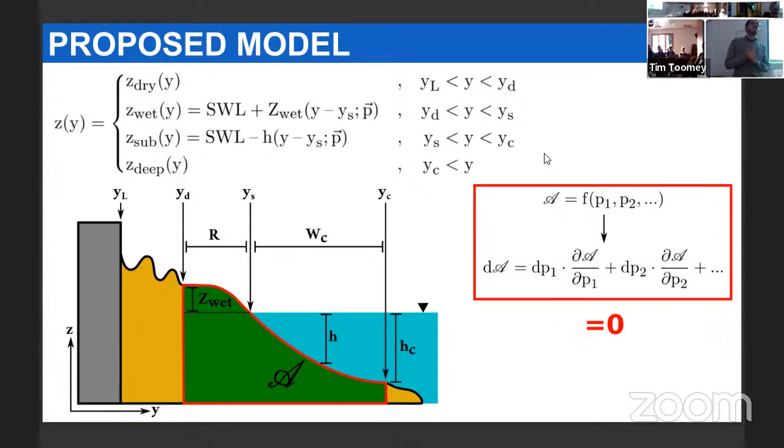I understand it's for solving the equations, but why do you? So the idea is to use this when we believe there's no significant change in the sediment volume that is within the beach. So for these cases that we expect there are changes in this amount of sediment, for example, beaches at river mouths or that are losing sediment, or that because of longshore transport can receive more sediment or lose it, then there are formulations which also add a term of a flux of sediment entering or exiting the profile.